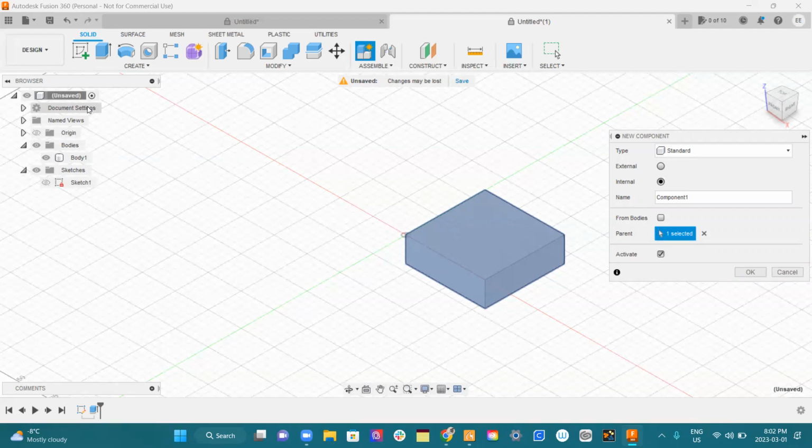Yeah, no. The machine does what it's told, and I'm going to tell it to start drawing on the top of the wood. So when I say to go, it's going to start at the origin, wherever that's placed. It's actually going to start in the middle of this block, and it's going to drill down, and I'm going to tell it to drill down 1 millimeter. The fact that this is 19 millimeters thick is irrelevant, except that when I'm modeling it, if I do want to cut all the way down through, you always mimic the thing as best as you can, because it helps this thing when it figures out how to do the drills, because it does that automatically.